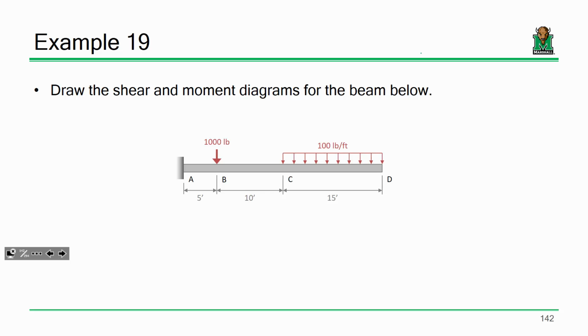Okay. Now, this one's going to be a little different, okay? The loads are easier, but we're going to find some things that might bug us a little bit when we do our analysis. For instance, when we draw the shear diagram, we're going to have a different result than we did last time. Remember how we computed all the areas? We got the areas equaled 0. You know, the area up top equals the area below. That's not going to be the case here, okay? They're going to be imbalanced. And there's a specific reason why they're going to be imbalanced, but we'll see that as we go.